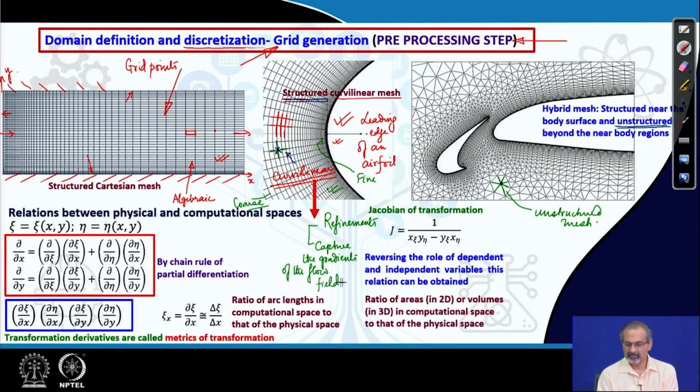You can very well understand that this kind of a mesh will be most well suited for a viscous flow calculation. So, a boundary layer will be formed on the surface, whether you are solving a problem like this on a flat plate or through a channel or over an airfoil, the boundary layer will be formed. So, the velocity variation will come up over here, and that too may be a very thin layer, if it is a high Reynolds number flow. So, you need adequate grid resolution. That is why a very refined mesh is used for the near surface region.